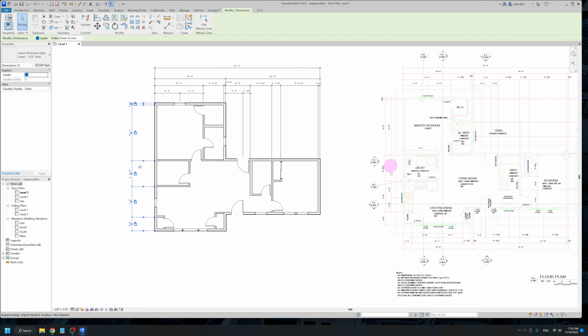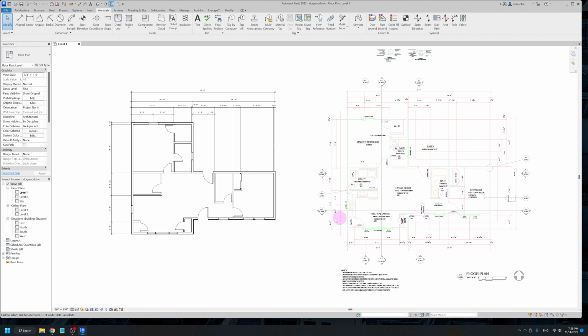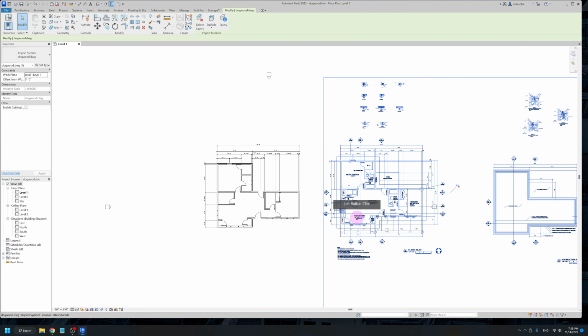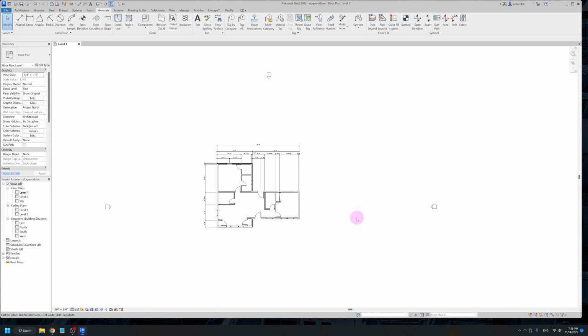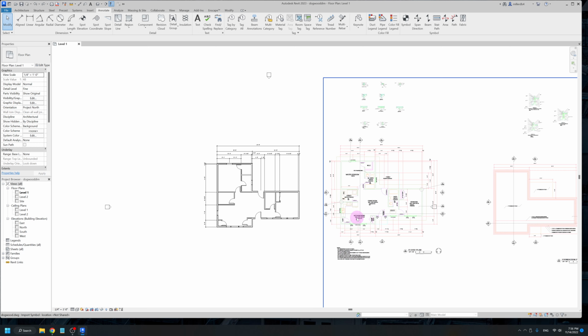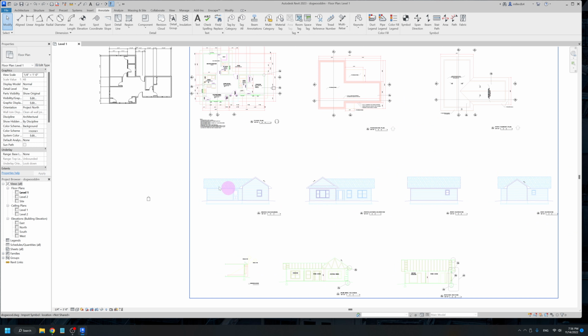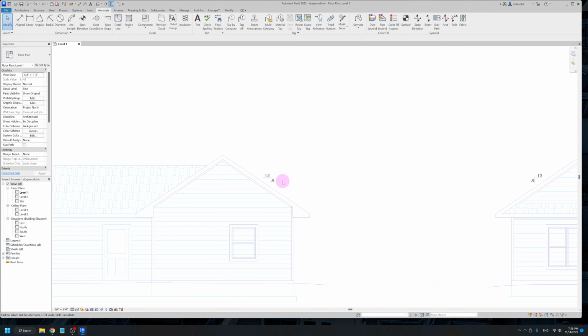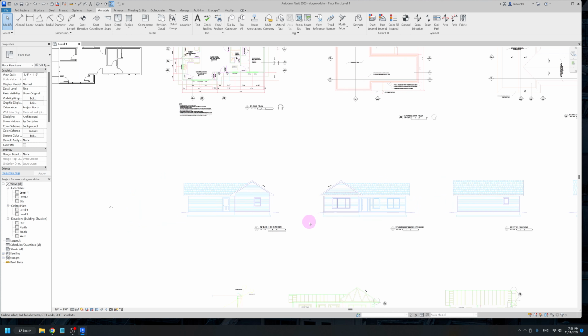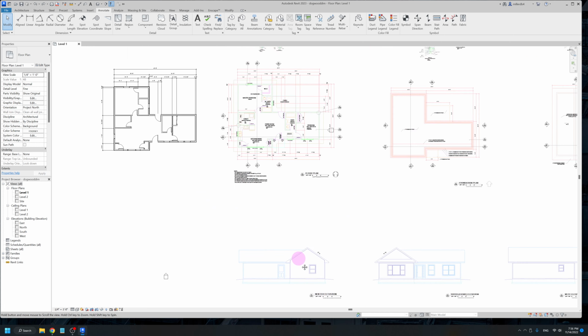And then I'll work my way in, and I'll just continue going around and placing all of my dimensions and locking them until I have every single one of them placed. And at that point, I'd be free to click on this CAD file and just completely delete it, because I would no longer need it to help build things like my floor and my roof. We'll reference, I just Control Z to bring the drawing back. We'll reference it to get the shape of our roof and the slope of our roof, but we're not going to need it to actually build the roof out. We're not going to click on these lines and reference them like we did in here.